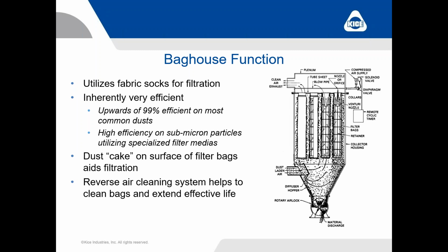And then again, this slide references the reverse air cleaning. We talked about that a minute ago. We have an air tank reservoir that contains pressurized air, and it feeds blast valves on a timing sequence in order to clean out one row of bags or one set of bags at a time.